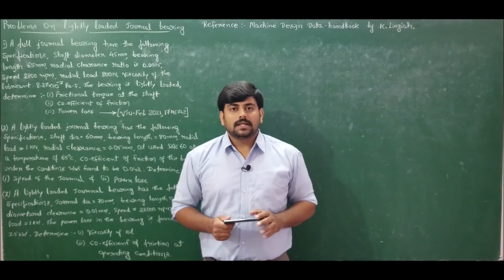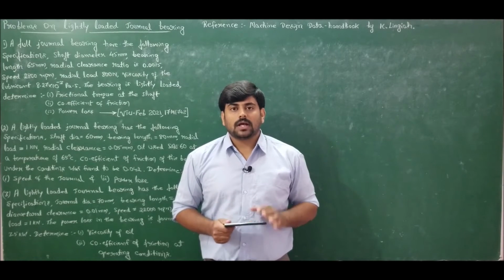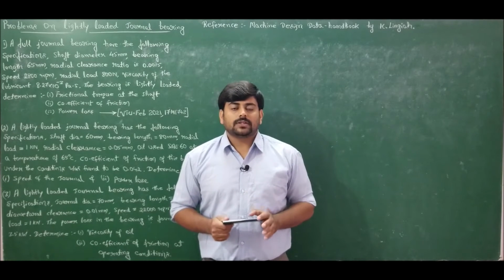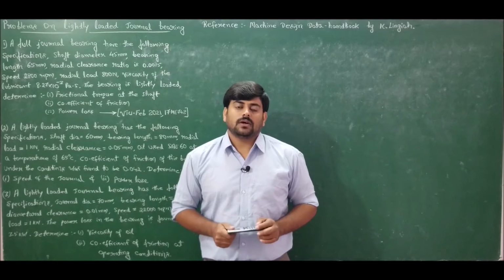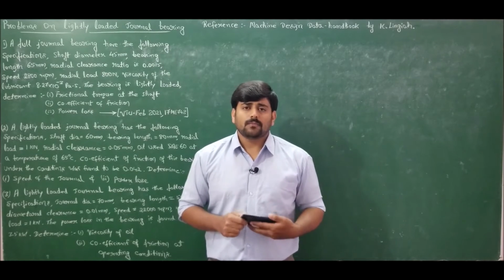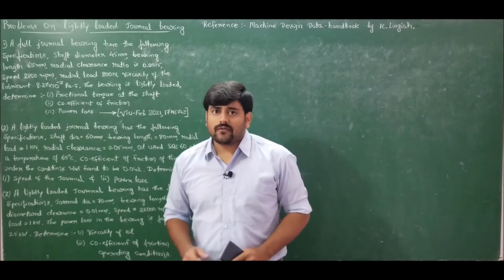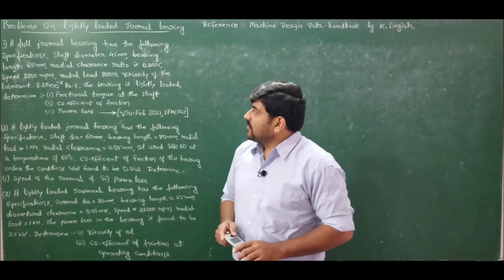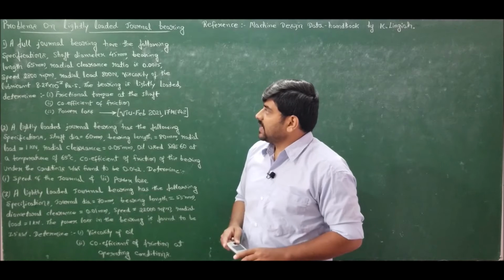In today's lecture, let us address numerical problems on lightly loaded bearings, wherein we can use Petrov's equation to determine the coefficient of friction of the lubricant oil. Moving ahead, problem number 1 of our discussion on problems on lightly loaded journal bearing states that a full journal bearing has the following specifications.